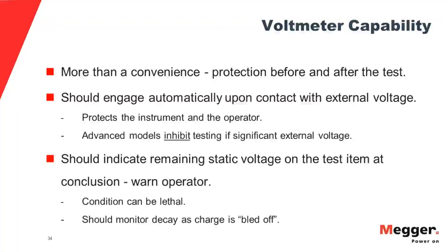So they will inhibit testing. And the other thing that they do, at the beginning of the test or during the process of the test, because sometimes someone will go and throw a switch, which you have turned off but didn't lock out, for instance. But at the end of the test, you also want to de-energize the test item. The tester is not dangerous. The test item can be, because you can store a large static voltage in the construction of the thing that you're testing. A big motor winding, a long run of cable has a lot of capacitance in it.